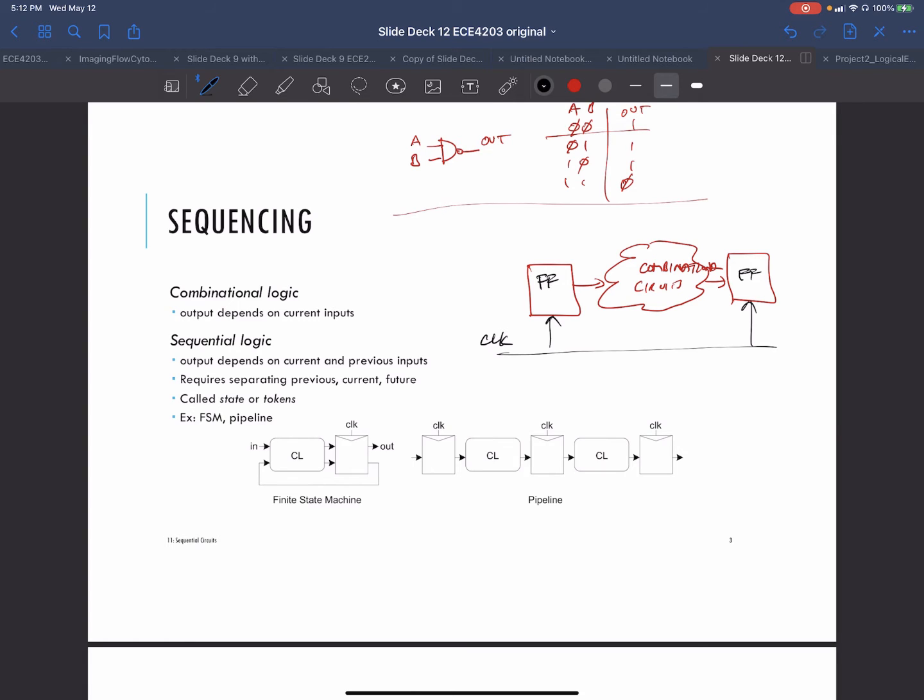So imagine how a finite state machine works for a vending machine. It starts at a waiting state, then you feed it some amount of money, and that takes it to a new state where it's waiting for your selection of your drink. Then you select your drink, and that takes it to another state where it's dispensing the drink, and then once it does that, it goes to another state where it's waiting again. So in each one of these cases, it has to remember what happened previously.